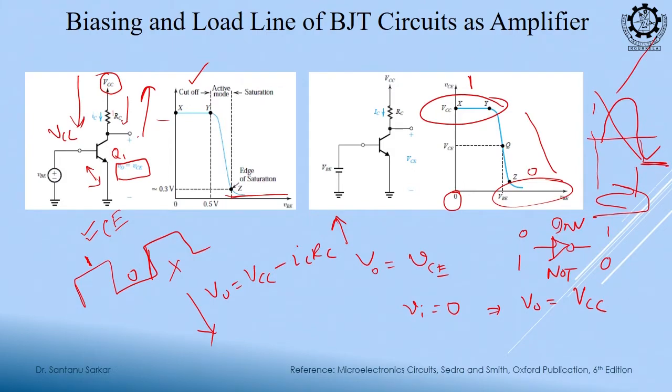Input voltage just above 0.5, 0.7: is the base emitter junction forward bias or reverse bias? Base voltage is above 0.5, 0.7, so it is forward bias, and when it is forward bias, large current is flowing and this voltage goes to 0 or close to 0. So, VC collector is less voltage than base. Collector base is forward bias or reverse biased? Reverse biased.